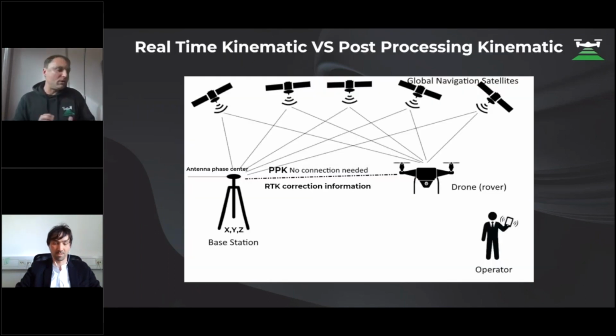Before showing you real projects, I would like to talk about why we chose PPK technology. You know that there are two different technologies. First of all, real-time kinematic, RTK technology, and the second one is post-processing kinematic. In general, everybody knows about RTK, but if we are comparing RTK and PPK, I would say that PPK is more accurate because you post-process data, you can implement additional filters, you can remove noisy satellites,